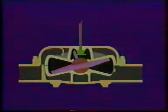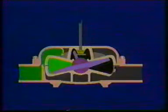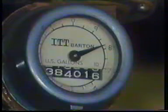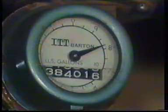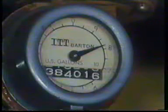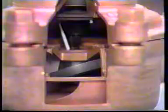The meter is connected in the system so that the fluid enters here at the inlet. The fluid fills this space and causes the disc to turn. The disc continues to turn until the outlet of the meter is opened. This specific volume of fluid is discharged into the system. Now, as the disc turns to transfer the specific volume of fluid from the inlet to the outlet, the counter drive pin moves the counter to keep track of the volume of fluid that is passed through the meter.